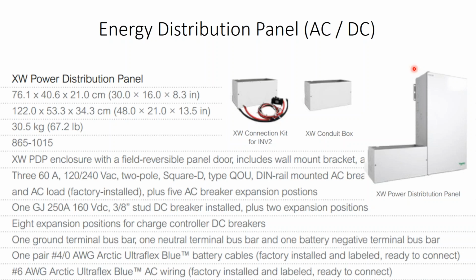And what that's going to be is a DC bus in a DC service panel rather than an AC bus in an AC service panel. And so your inverter manufacturers will sell you a service panel to provide that DC combined connection. And then Schneider, and what's common on your battery inverters, they'll also put an AC side on that service panel.